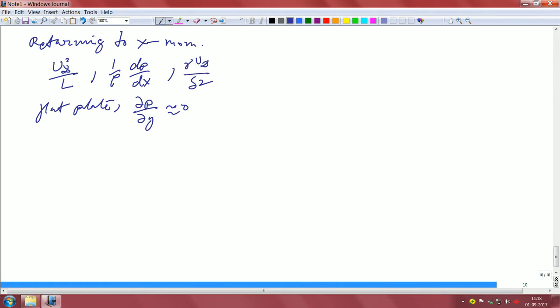That is what we proved, right. Okay. So, this leads to p being a function of x only, that is how we could write it as dp by dx, the ordinary differential. Okay. So, let us consider if this is the case, that means pressure anywhere in the flow field will be only a function of x, it will not be a function of y, right.